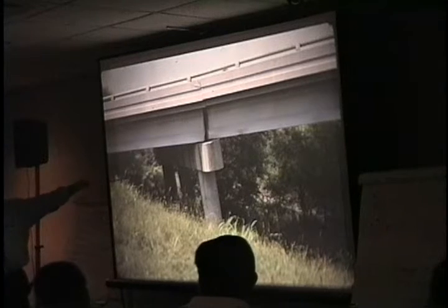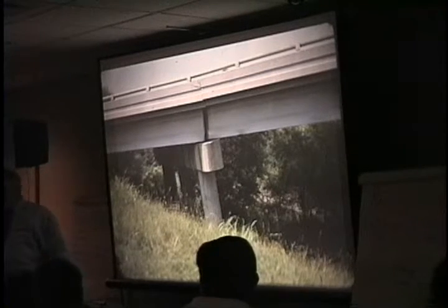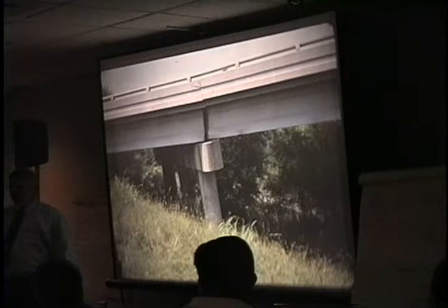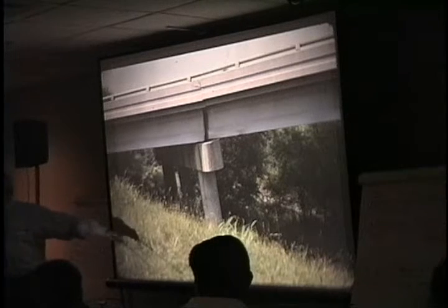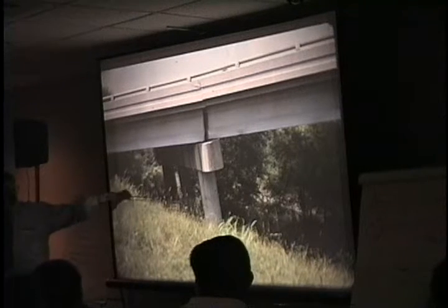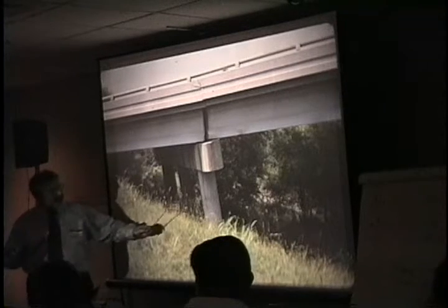Started to see cracks around the side slope. Of course, I knew right away from my own experience that when the water drops quickly, rapid drawdown, the soil becomes twice as heavy and you're more likely going to have weaker resistance along the shear plane, but increased driving forces. And what happened there, swear to God, this is a true story.